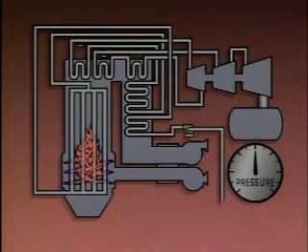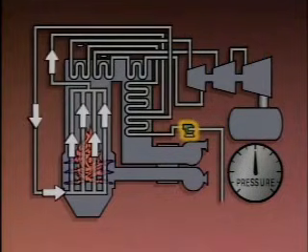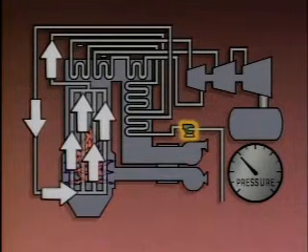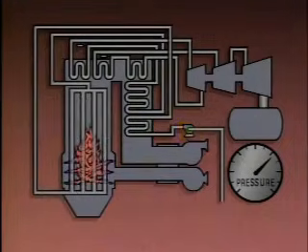That's because the pressure in this type of boiler is controlled primarily by the boiler feed pumps. If the pressure produced by the boiler feed pumps is reduced, the steam pressure will decrease. If the pressure produced by the boiler feed pumps is increased, the steam pressure will increase. Lowering the firing rate in the furnace of a once-through boiler will only cause the temperature in the water walls to drop. Pressure is not significantly affected.